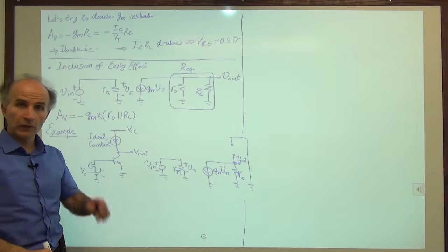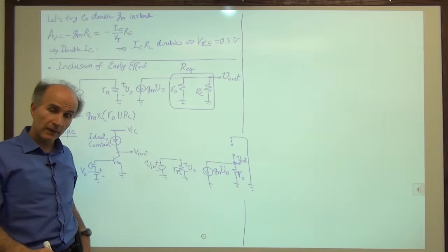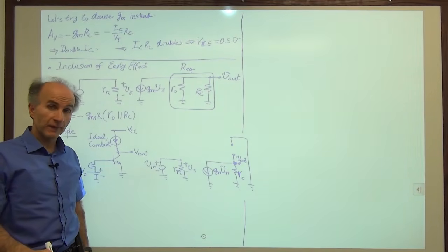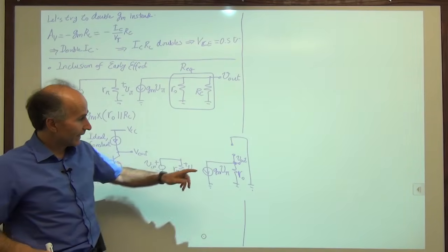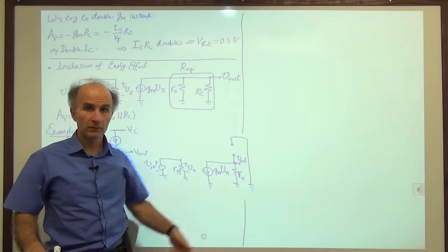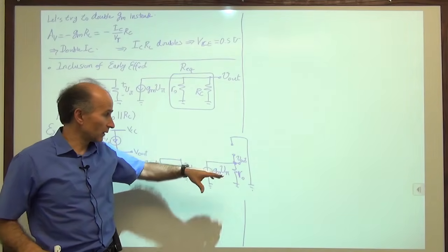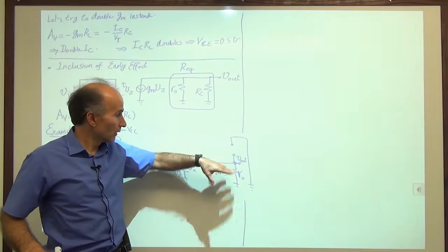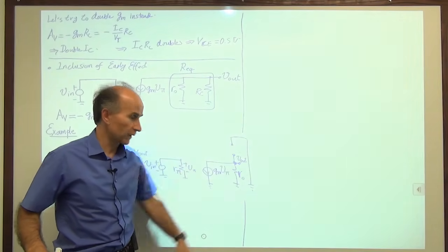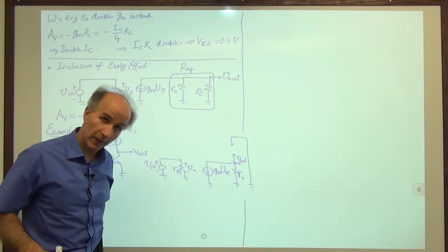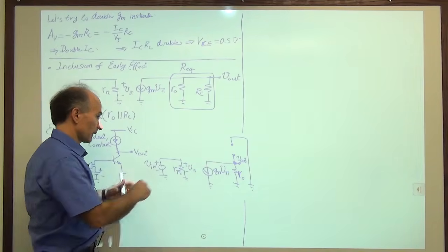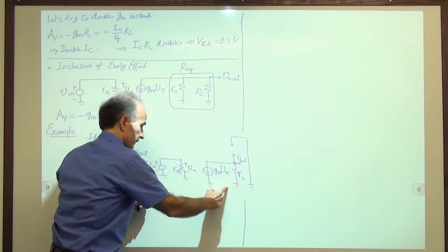So, again, before writing equations, we just take a look and see what this tells us. Can we simplify it? What's the significance of this open circuit here? Nothing, it's gone. It doesn't draw any current, so we can just forget about this piece of wire here. If you forget about that piece of wire, what we have is just this nice little circuit.